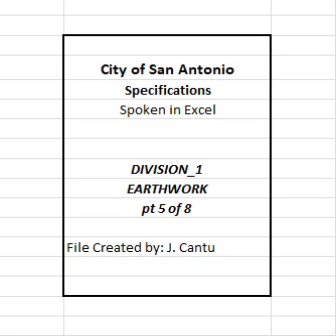When ordinary compaction is specified, roll and sprinkle each embankment layer in accordance with section 107(3)d. 1. Ordinary compaction. When density control is specified, compact the layer to the required density in accordance with section 107(3)d. 2. Density control. When rock and broken concrete are allowed in lower layers of earth embankments, proof roll these layers as directed where density testing is not possible, in accordance with TxDOT Item 216, proof rolling, to ensure proper compaction.